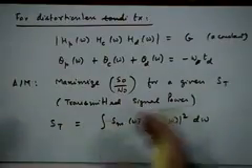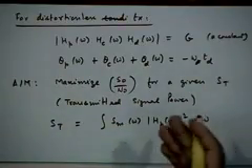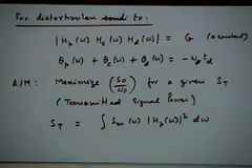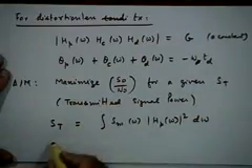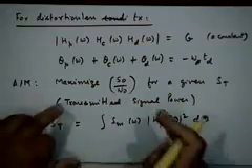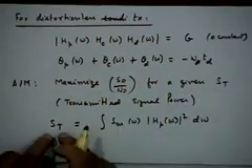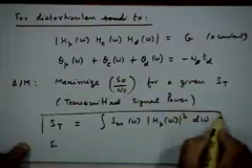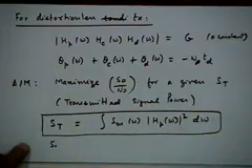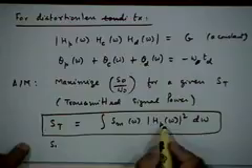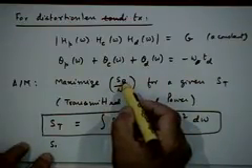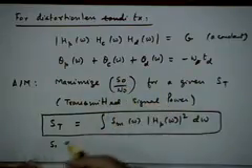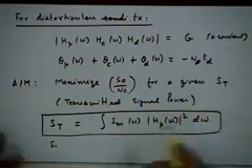The area under that is the total message power that is being put on the channel, right. Let's assume that the channel does not attenuate. In any case, the attenuation factor can be taken into account separately in fixing the S_t value. So your problem is to maximize your output signal to noise ratio for a given value of S_t, which can be written like this, which depends on H_P. Okay. So now to do this, you must write the expression for output signal power, output noise power, take the ratio and maximize. That's what you need to do.